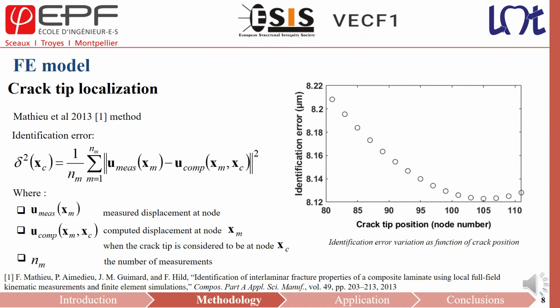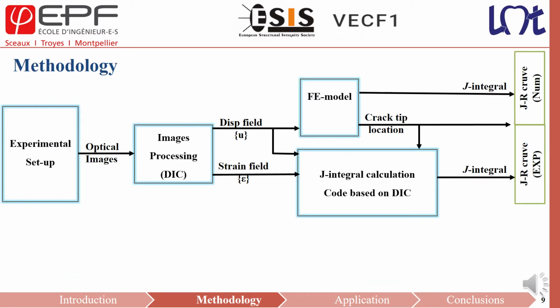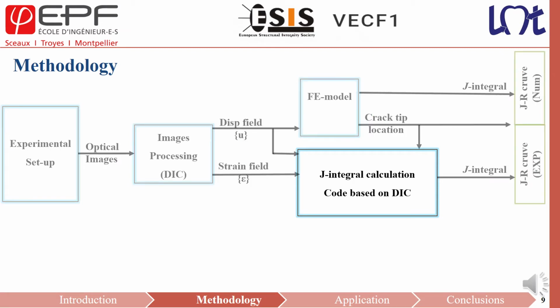The FE model gives the crack tip position, but it also evaluates the J integral with its built-in procedure. Another route to calculate J integral is provided by the method based only on measured kinematic field that I will present now.